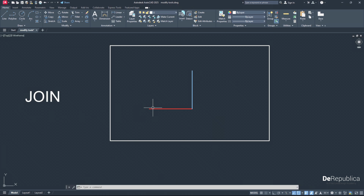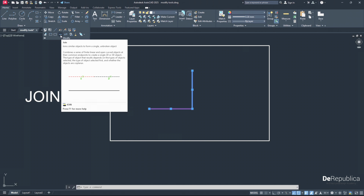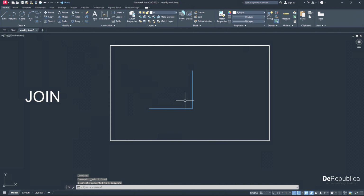In my previous tutorial, I explained something about line and polyline, where anything drawn with line consists of different lines. They are not joined. I want to join this line with this line. Instead of making two selections, I want it to be selected with one click. To do so, select the two objects, go to the Modify Tools panel and find this arrow, and then this icon here represents the join command. Click on it, and as you see, I merged the two lines into one line. If I click on it, I have to do only one selection in order to select the whole line.